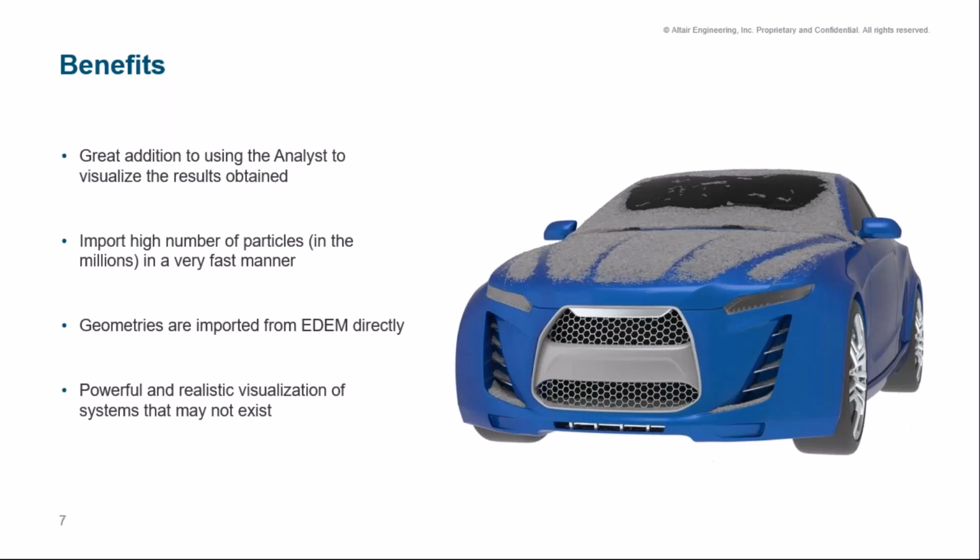It's actually very, very efficient in importing a very large number of particles. So generally speaking, the number of particles that you run in EDEM, it's feasible, to my experience, to just import it into Inspire Studio. It tends to be quite fast as well due to the method they use for representing the different particles. And then the additional things is, first of all, when you are importing your EDEM files, your geometries will also be imported with it.